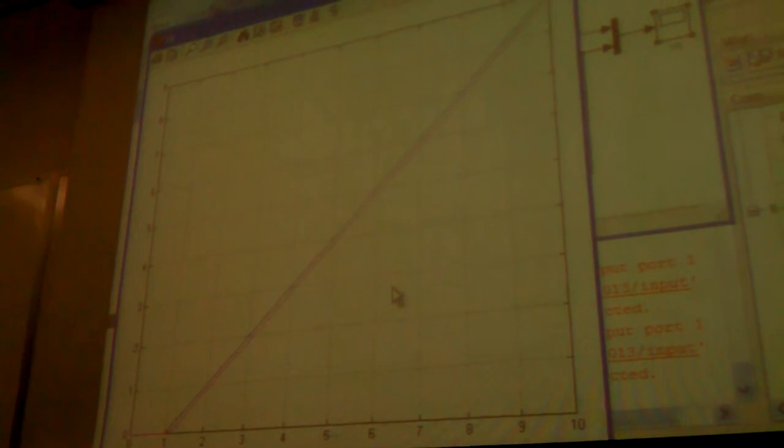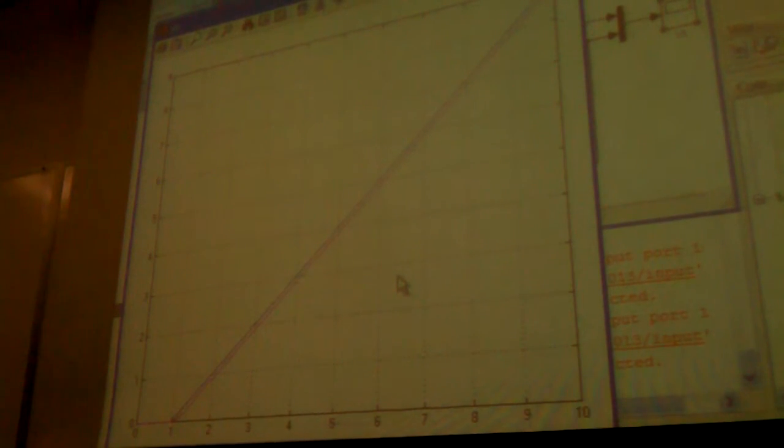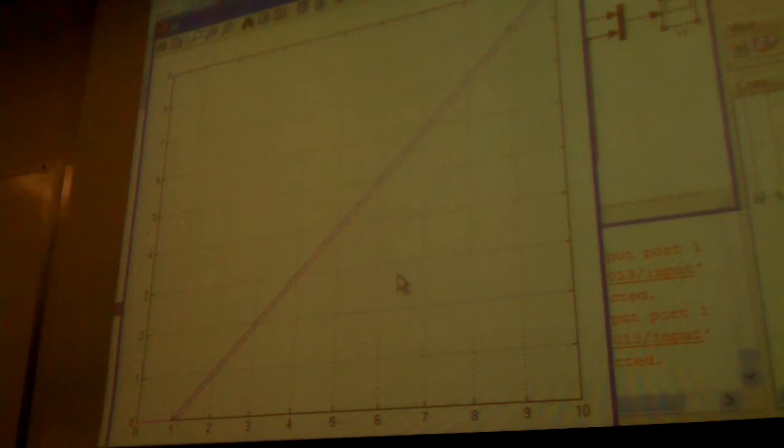To get rid of the steady-state error, you need to add one more integrator, then it will be gone, for a ramp input. But you have to be very careful because two integrators give a 180 degree shift, and with time delay, this can cause problems. So be very careful with that. Theoretically, you can get it done, so you can show those kinds of things and verify that, okay?